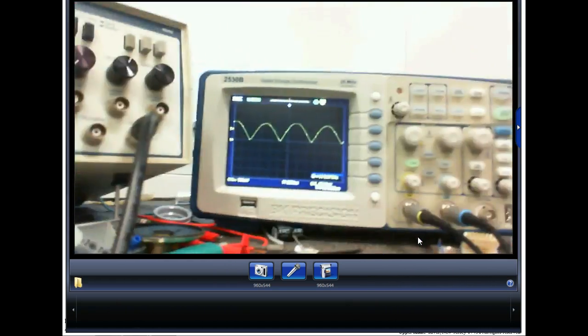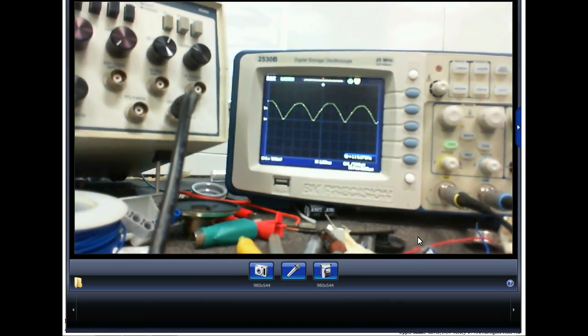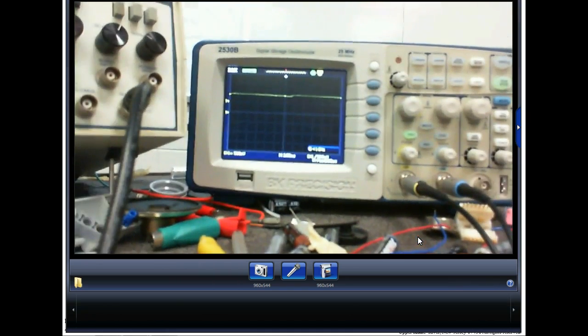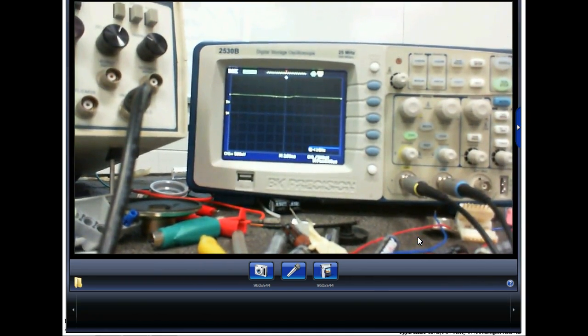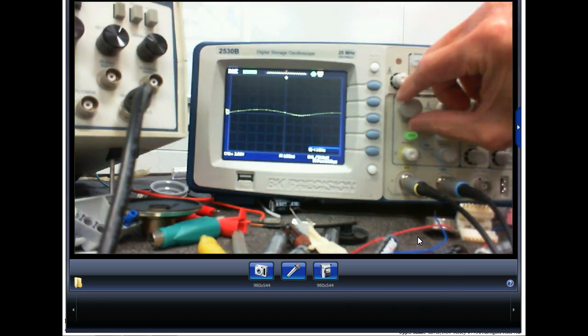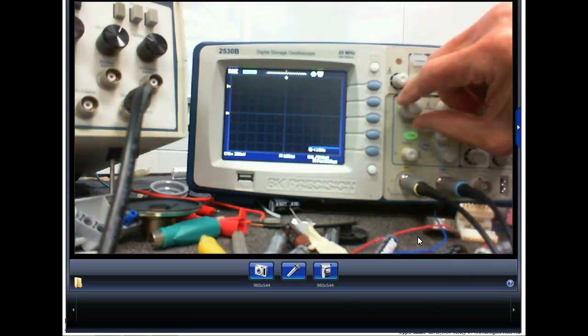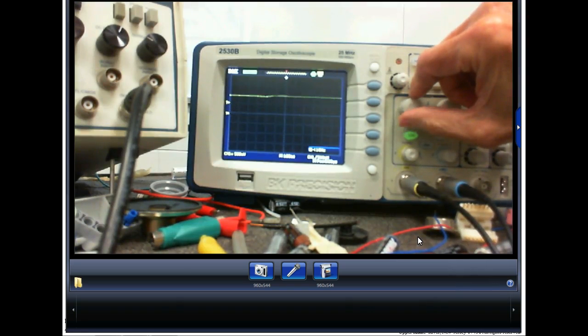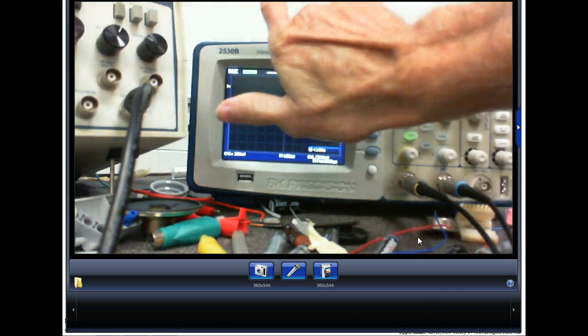Well, we're still not quite there yet. Of course, if I come over here and put the capacitor across, got to honor the polarity on the capacitor. And I'll show you a video, by the way. And all of a sudden now we got DC, but look how much cleaner it is. And that's the same size capacitor. It's still there, and we'll show y'all how to see that when we get here. There's still what we call a ripple voltage, but the problem is I can't see it. And if I turn it up so I can see it, my display goes off the top.